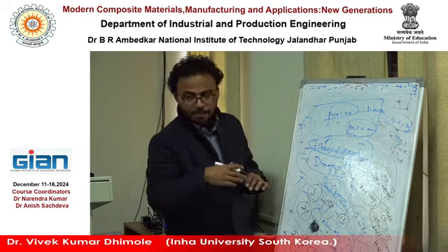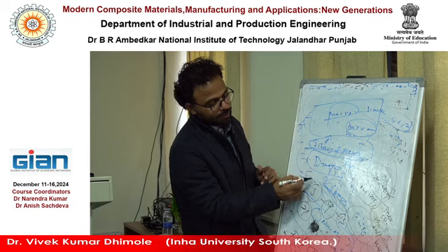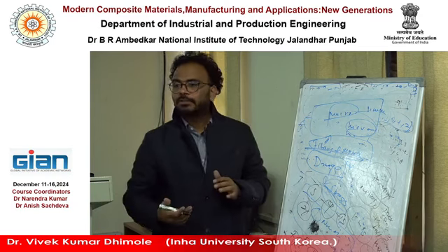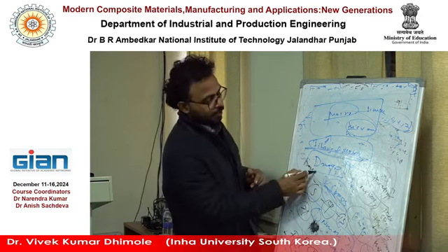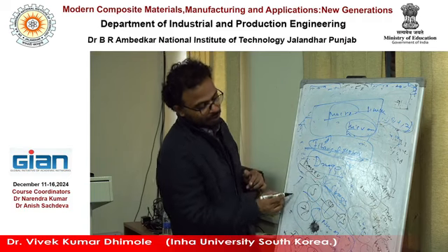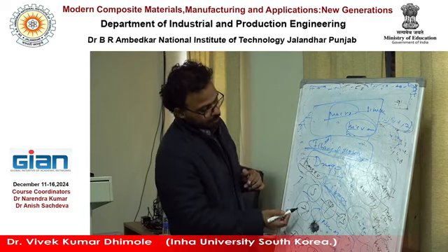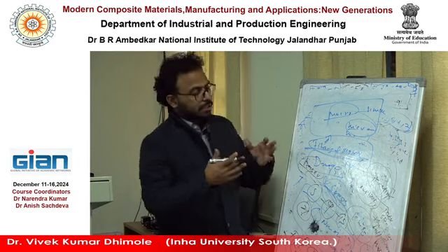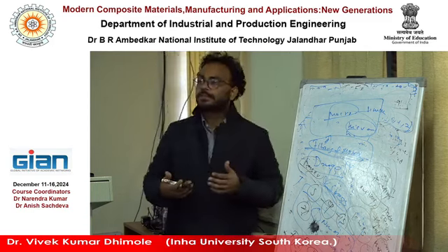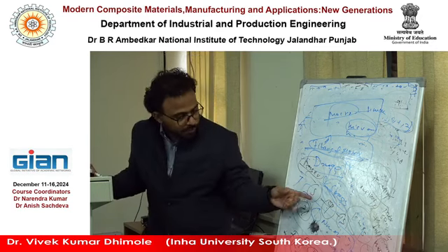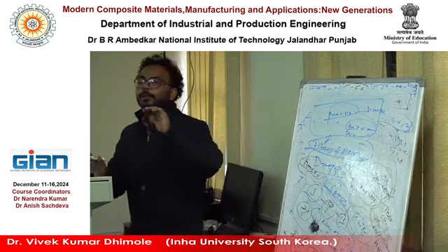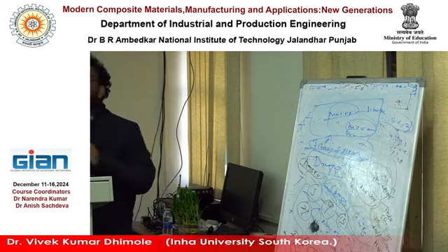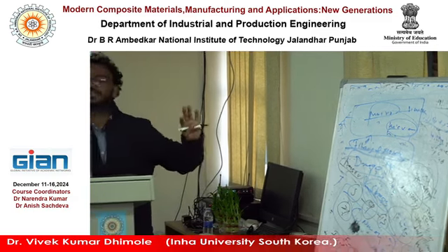Many times we use carbon fiber, glass fiber, aramid fiber, we use transversely isotropic, right? Two plane symmetry, one plane symmetry, then no symmetry, right? Something like that. So based on symmetry, the constants of the 4th order tensors are reduced. So we use this one or this one depending on that. We give the properties of the lamina or the engineering constants, okay? That decides the material system.